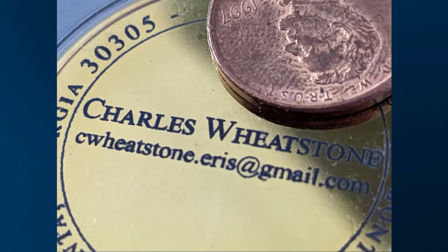All right, now, I mentioned earlier that your galvo fiber lasers are used for marking metal and that your CO2 lasers can't really do anything with metal. The wavelength that a CO2 laser produces is reflected by metal. Now, you cannot etch the metal, but you can mark it in other ways. So here we have a brass coin, and we have a penny here for scale. The text that you see is not engraved.